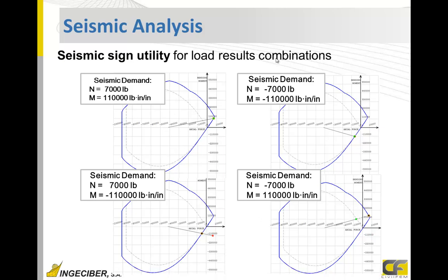If you combine it with ANSYS, you can have all positive, and you can multiply by -1 and have all forces negative, for example axial force and bending moment both positive and both negative. This is the typical procedure if you don't have CivilFEM.